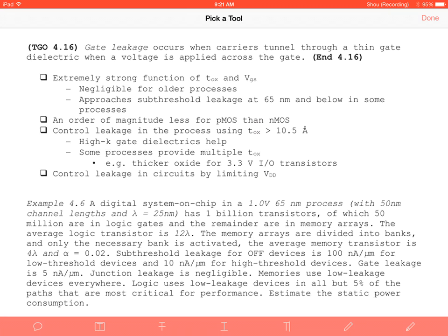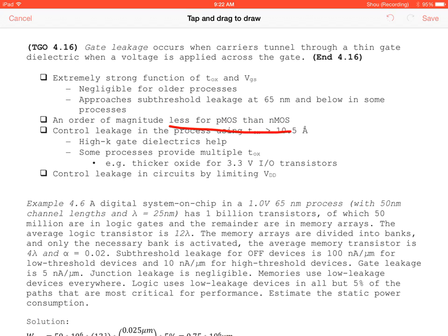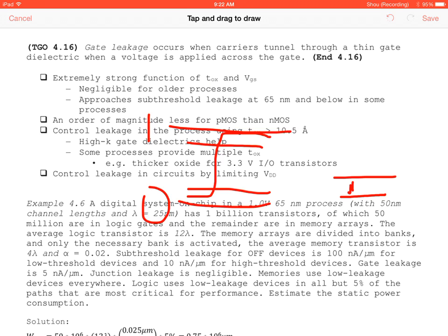If you guys don't think about it, I'll just say it. One of the issues that we're having with implementing graphene is because you have to have some sort of logic 1 and some sort of logic 0, right? And we learned noise margin. We have to be able to create some sort of change to get from that logic 0 to a logic 1. Graphene's switching, there's not much difference. So they have to combine graphene with other silicon technologies to try to create this difference between 0 and 1. Ultimately, in digital logic, we have to tell the difference.